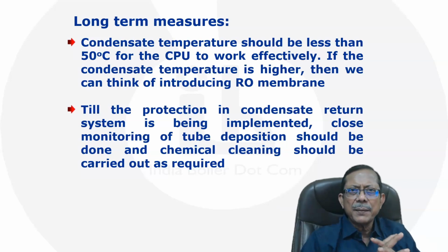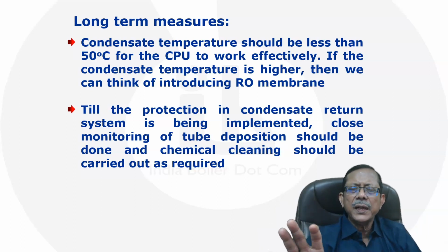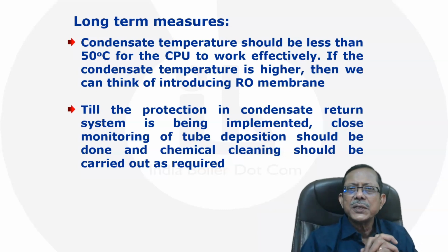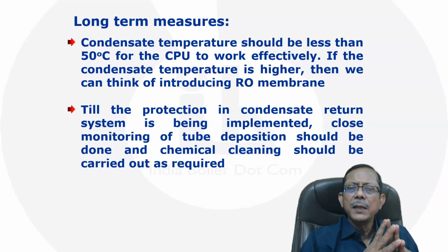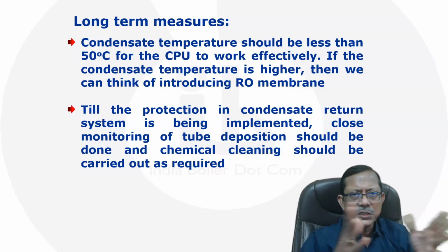And if that is happening, then the boiler is going to get dirty and the corrosion sites are going to be created. So time and again they will have to look for such deposits, right, and go for chemical cleaning. In fact, interestingly, I will share this, that when I saw their OEM guideline, they have suggested to go for acid cleaning every 3 years, which is something very odd.